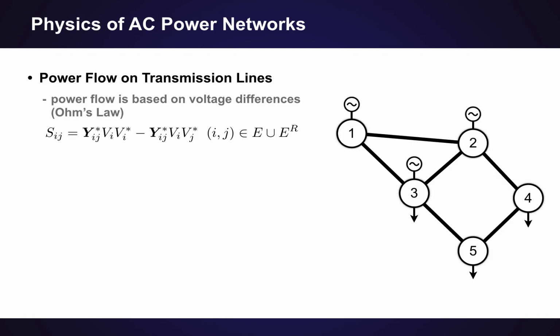Yes. So I will continue by talking a little bit about how you combine these power lines into the physics of the whole network system. So we have transmission lines in our network, as we saw before, and we have the admittance data. And now, by using Ohm's law and the definition of power, we have this equality constraint, which tells us how the power is defined on Sij for every one of these edges in the power network.